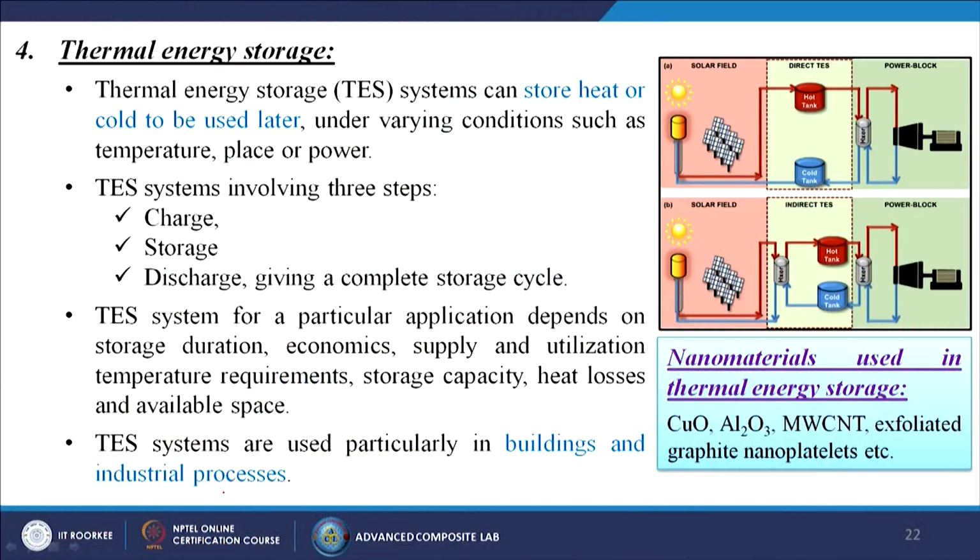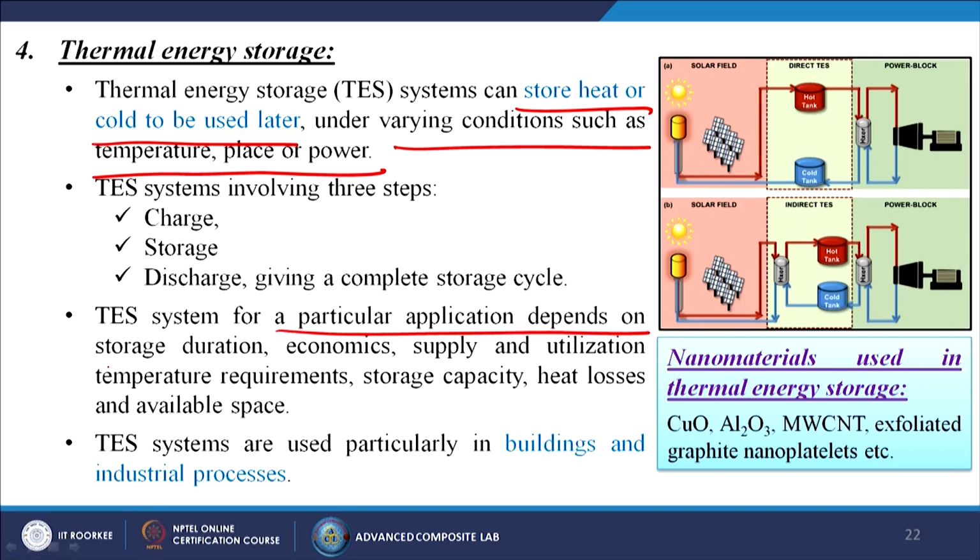Next one is called thermal energy storage, in short TES. Systems can store heat or cold to be used later under varying conditions such as temperature, place, or power. TES also works in three different steps: charge, storage, and discharge, giving a complete storage cycle. The TES system for a particular application depends on storage duration, economics, supply and utilization temperature requirements, storage capacity, heat losses and available space.